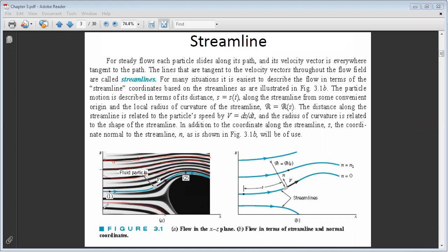These lines represent the trajectories of particles, and you can consider that these lines are formed by the velocity vectors of your particles. So by definition, your streamline is just obtained by joining tangent lines, so by joining velocity vectors. This is why we can define the streamline in this way.